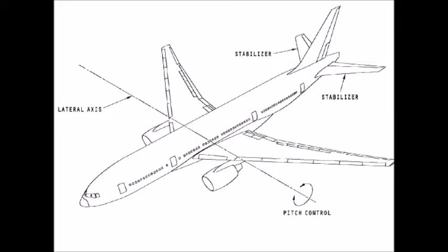There are 4 PCU attach fittings on each elevator. Jumpers and static dischargers supply electrostatic protection. The elevator surface deflection limits are at the PCU internal stops. The elevators have a maximum movement of 33 degrees trailing edge up and 27 degrees trailing edge down under no load conditions. Under load conditions, the maximum PFC and ACE command signals move the elevators to a nominal position between 30 degrees TEU and 25 degrees TED.